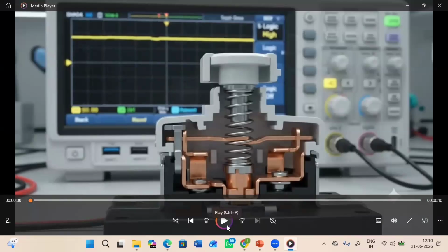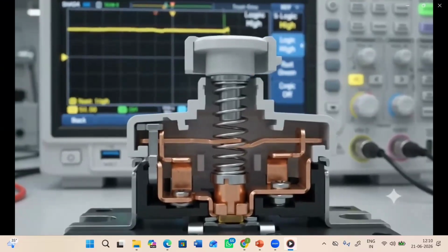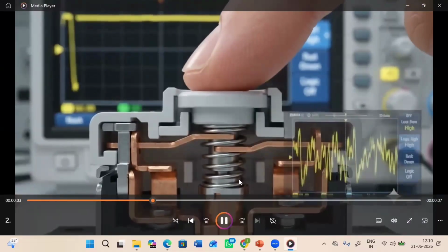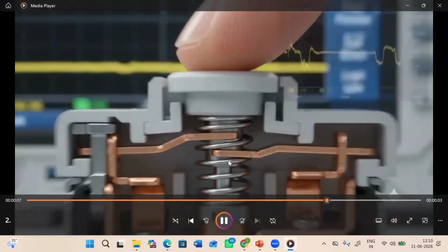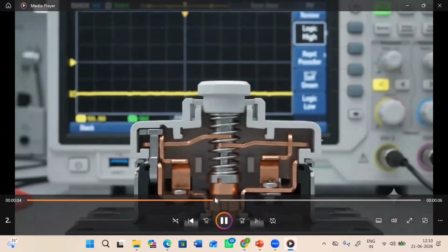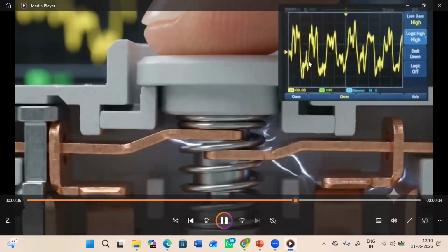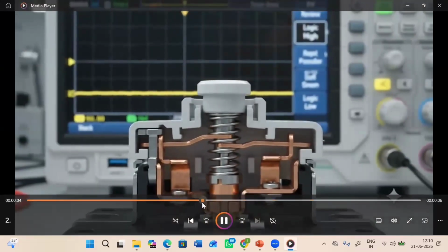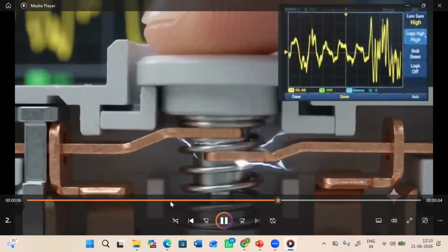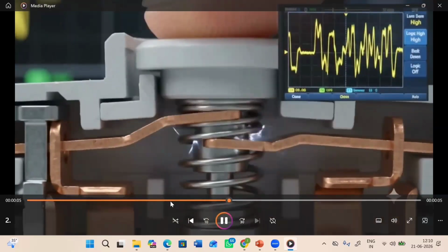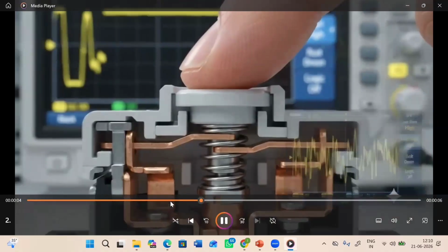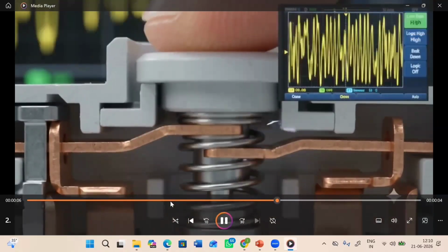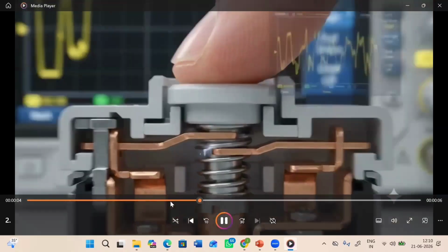Things wouldn't get clear in college, right? See here very carefully. As you press the button, it goes to the next state. But in between, there are stages of high, low, high, low, high, low. You can see the waveform on the oscilloscope screen. The button never goes cleanly to the low state. Due to the mechanical arrangement, the button continuously flickers in its state, as you can see very clearly on the screen: high, low, high, low.